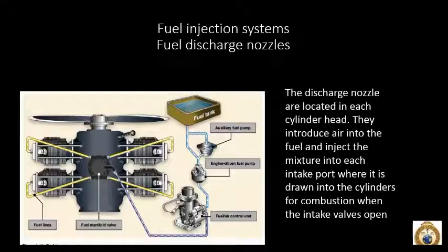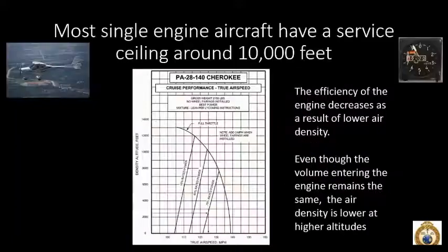We talked about the discharge nozzles. The discharge nozzles are located in each cylinder head. They introduce air into the fuel and inject mixture into each intake port, where it is drawn into the cylinders for combustion when the intake valves open. So there are still valves there.